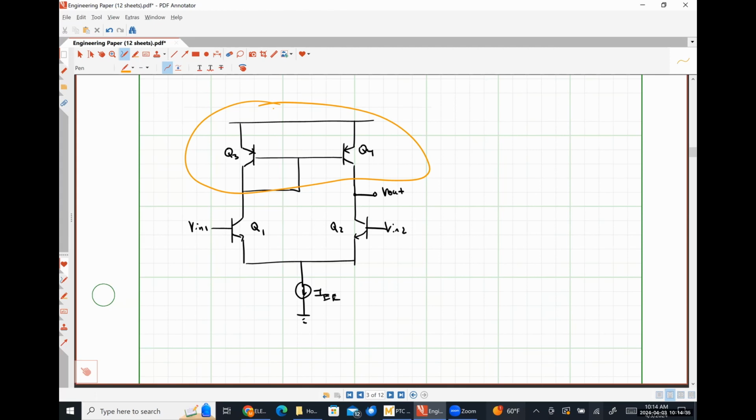We usually call it an op amp. This is a single stage op amp. We take a differential input voltage and convert it into a single-ended output stage. Now, this is a really bad op amp in as much as it can only drive capacitive loads because of what its output resistance is. So we might chain this into another amplifier to provide more voltage gain and give us a better output resistance.